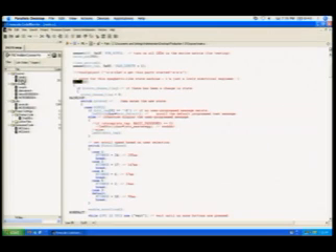Most embedded applications will have an infinite while loop and a driver stack, and it'll go round robin through each driver and determine what messages it needs to send based on all the global data it has. Now, in the application world, you hear that global data is bad. On an embedded device like this, there's no dynamic memory allocation. Everything is going to be determined at startup, and anything that dynamically allocates memory could crash your device, especially if you're doing safety critical applications. You don't want any of that.